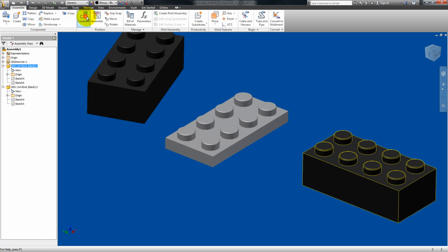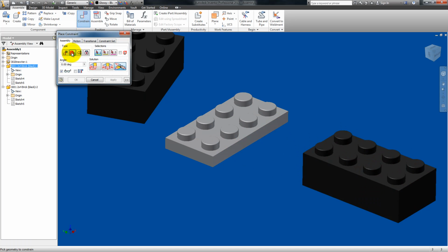What else we got? So basically for the angle constraint, you've got a couple different solutions. So direct angle, undirected angle, and explicit reference vector. Basically what you do is you just pick angle and then you pick your three selections, so 1, 2, and then 3 for example, and then you pick your solution. So for this one you'll only have 2, as I just illustrated.